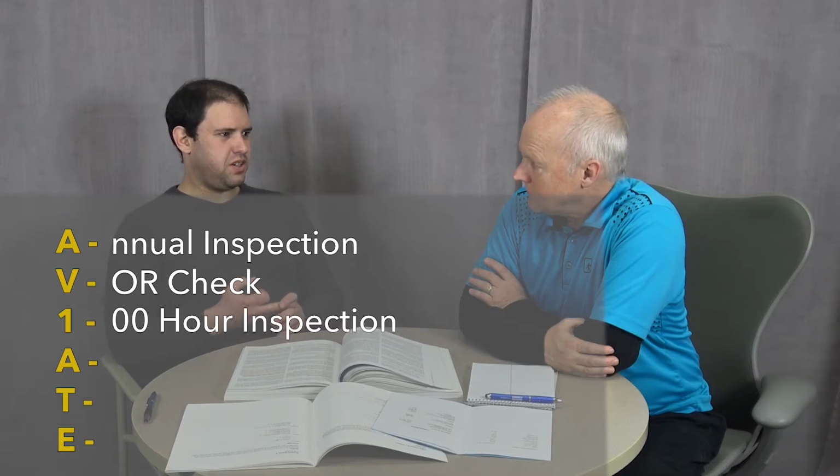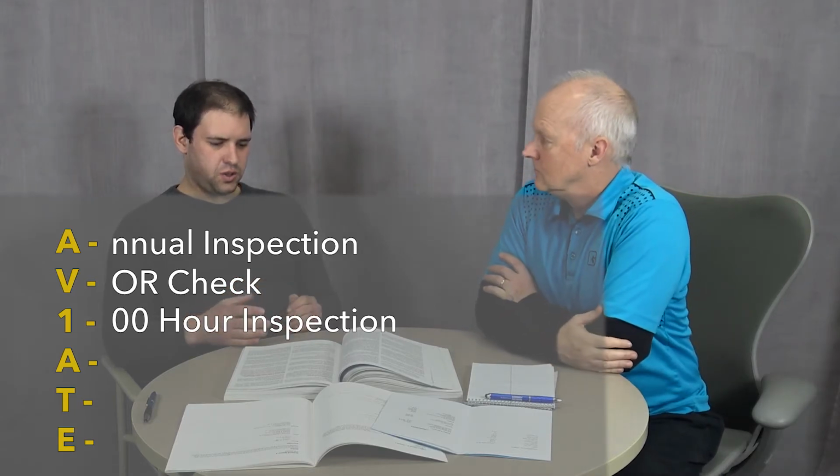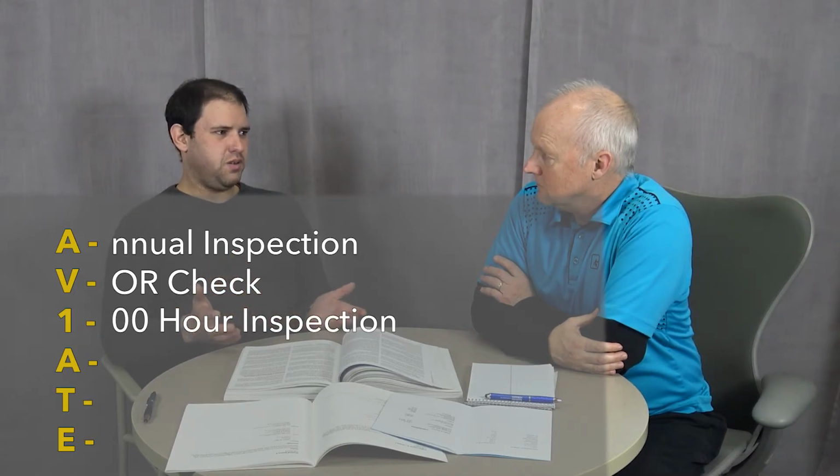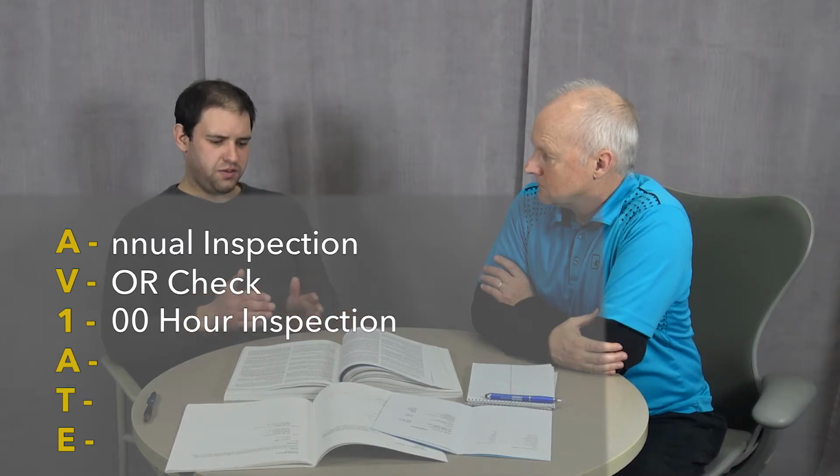The next one, the I in AVIATE, is the 100-hour inspection. So this is sort of a slightly less comprehensive version of the annual inspection, but it has to be done every 100 flight hours if the aircraft is being used commercially. So if it's being used for compensation or hire, the aircraft has to have a 100-hour inspection. Now, this gets a little bit complicated because if you are flying a privately owned airplane, obviously that's not flying for compensation or hire.